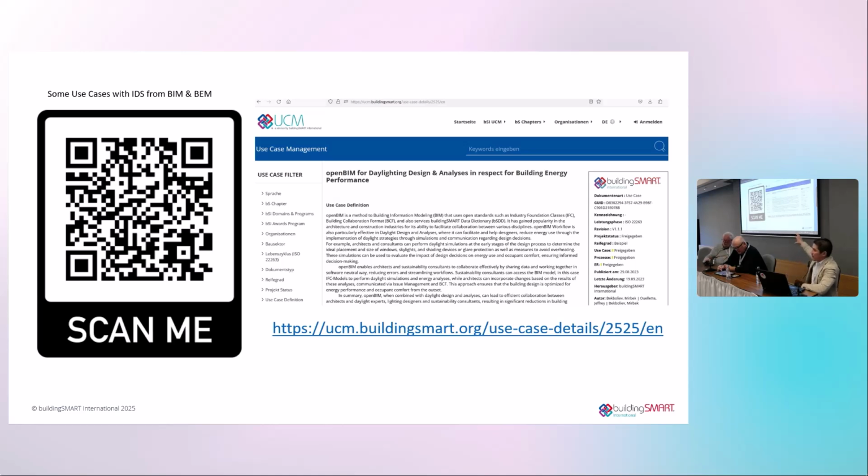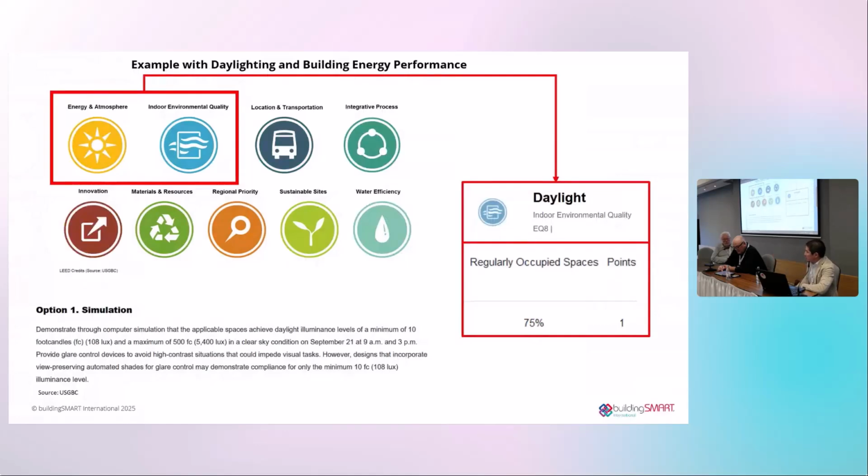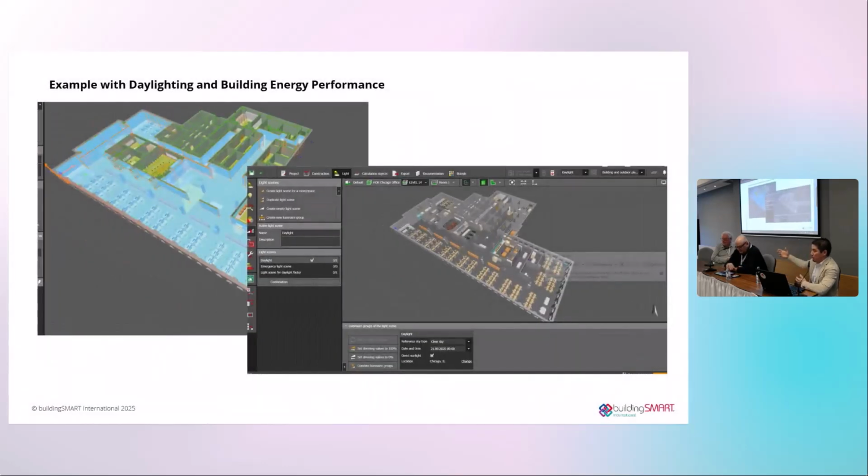We had exact requirements that we need to have openings, so windows should be properly mapped with IFC window, IFC curtain wall, and IFC building envelope, meaning the walls and spaces that we have to deliver. What for? Because sometimes in the US, clients decide, oh, we want to have LEED, whatever, LEED 4, LEED 5 now, I guess, and potentially you can get credits after that.